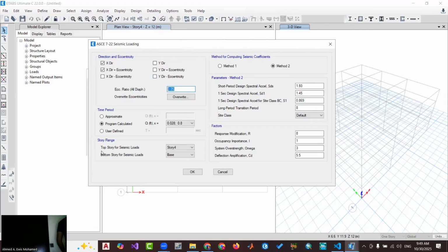Yeah. For the center of mass, the earthquake applies on this center of mass. Center of mass is the center of mass of this floor. Where is the mass of this floor? It's only the slab itself, and also the weight distributed on it, and also half of the shear wall or column from the bottom story and upper story.